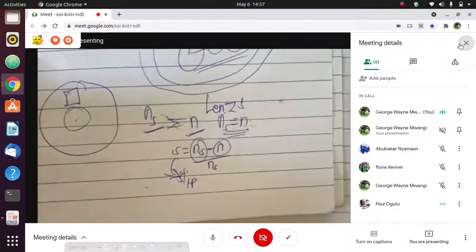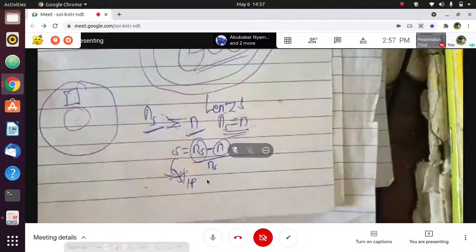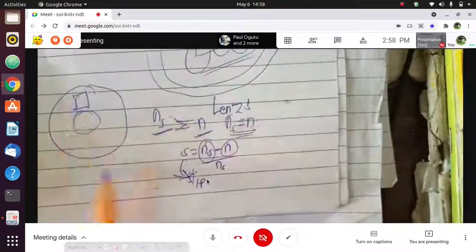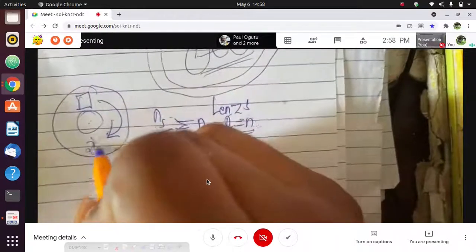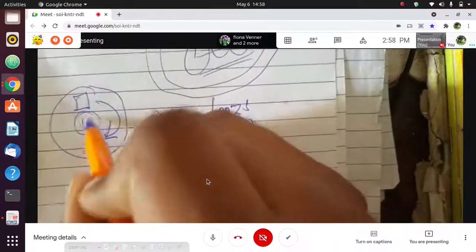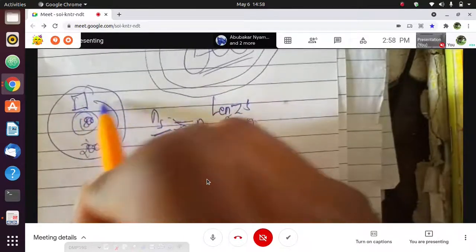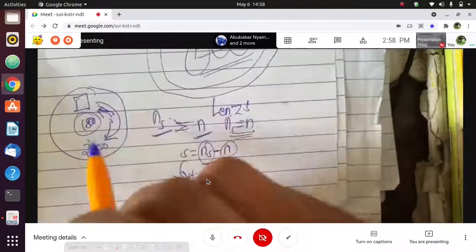Okay. Now, when you are sitting on this rotor, you'll see that the speed of the rotor is slipping behind the speed of the rotating magnetic field. So, if this is rotating at, let's say, 2000, and this is rotating at 1800 RPM, of course, kama umekalia hii rotor, utapata kwamba ni kama inaachwa nyuma. It's like it is going behind.